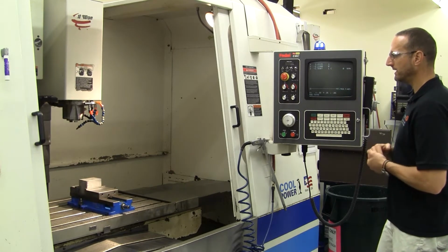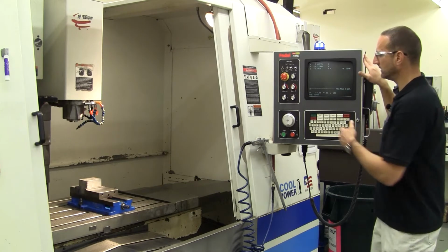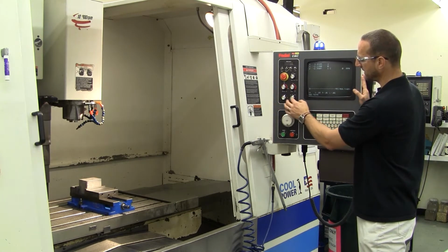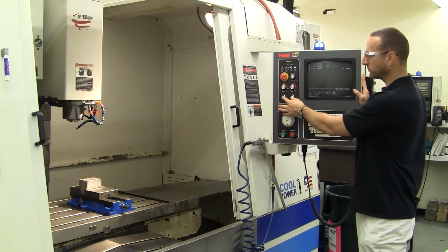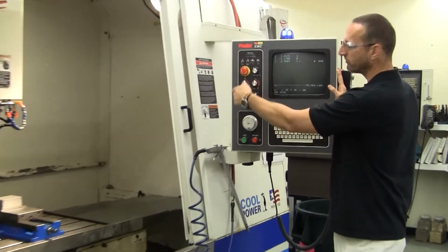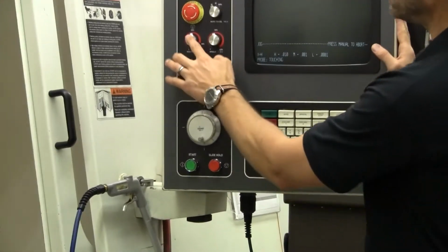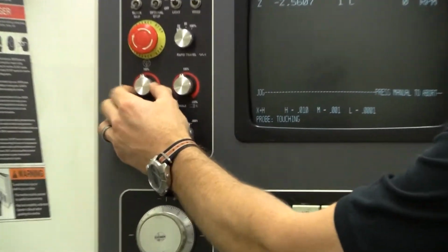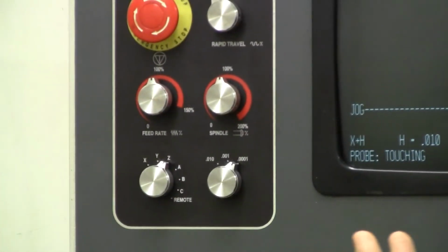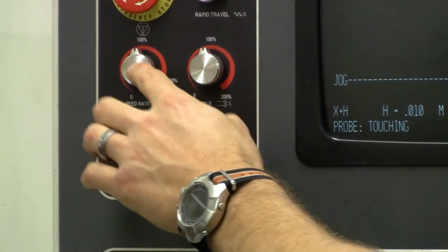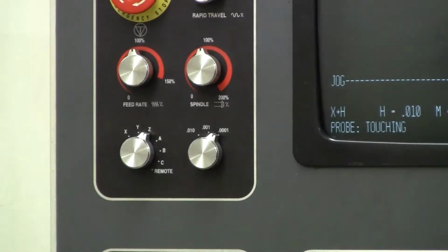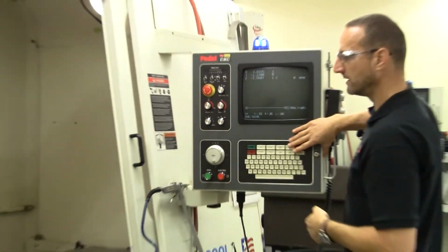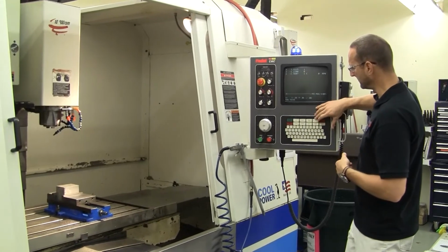One other thing to note that is advantageous at this point is also this dial right above our axes and increment selector switches. We have two other dials. These are known as our override switches. We have one for feed rate and we have one for spindle speed. And these are essentially always active, meaning right now, if I was to reduce the feed rate override, it would affect the rate that I am traversing the current axes with my continuous jog mode.